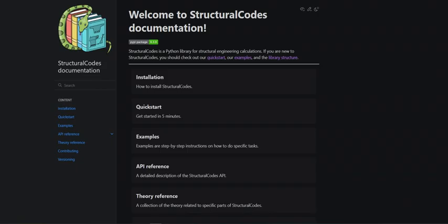Yeah, I think those are good observations. There's also a difference in where you apply the partial factors, isn't there? In at least Eurocode and the fib Model Code, we tend to have the partial factors on the material properties, so that's what enters our section calculations inside structural codes.